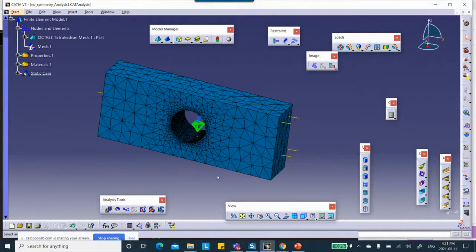But imagine that both of you were sitting in the back of a truck, and the truck was moving, and you were pulling on this thing. So you don't know how much displacement each node had, because the truck is moving as a rigid body. This is in equilibrium. However, there are no restraints. That's why it's moving as a rigid body.